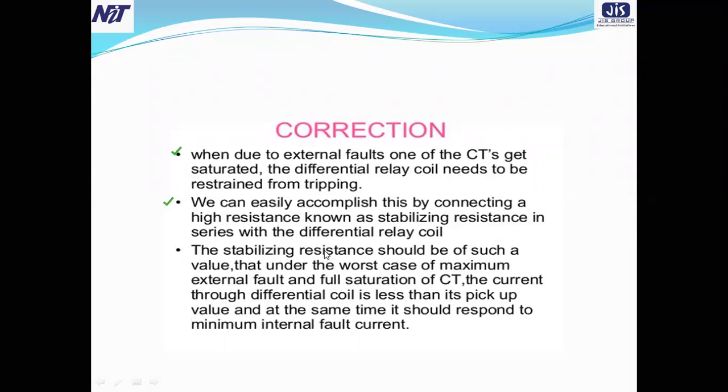So on the operating principle, we can apply the operating principle of the differential relay. We can understand how this problem we can solve. Here we can easily accomplish this by connecting a high resistance known as stabilizing resistance in series with the differential relay coil.